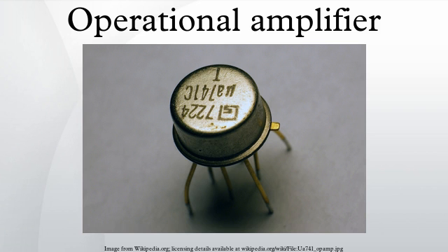Limited dissipated power. The output current flows through the op-amp's internal output impedance, dissipating heat. If the op-amp dissipates too much power, then its temperature will increase above some safe limit. The op-amp may enter thermal shutdown, or it may be destroyed.